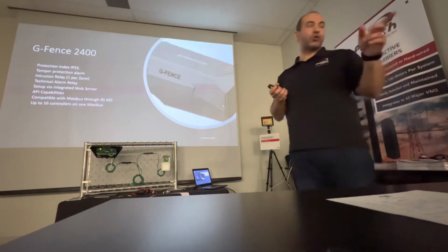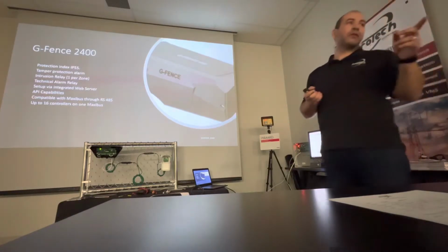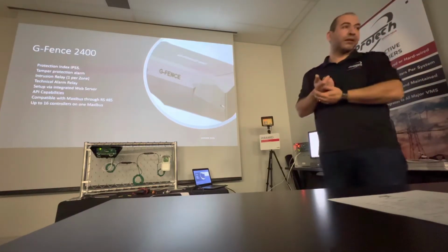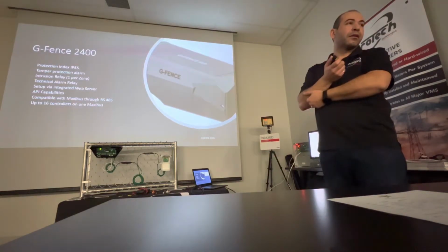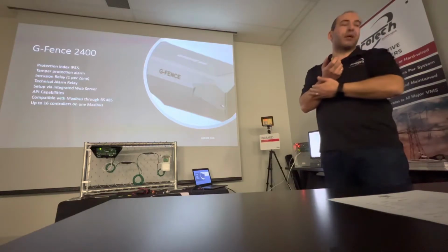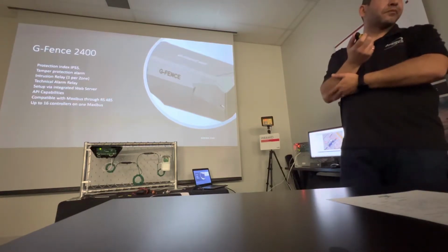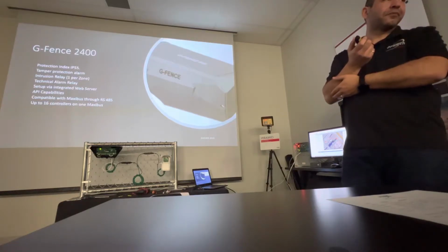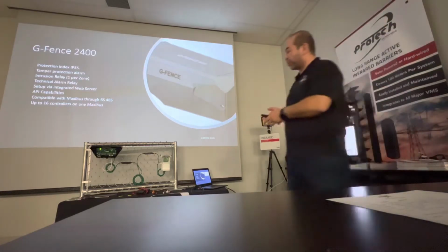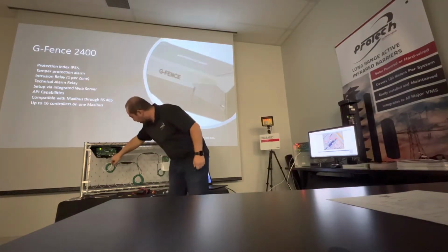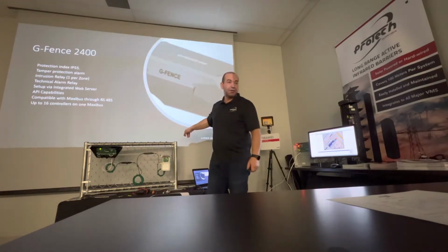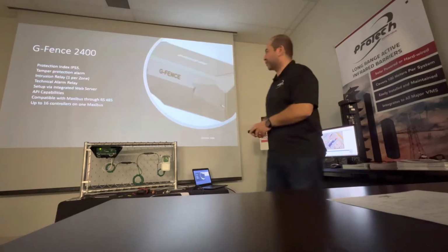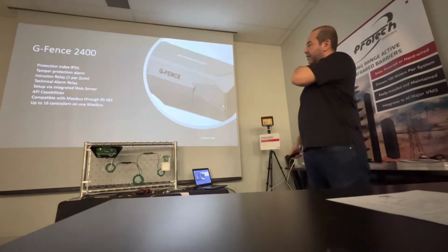Exactly. If you put the control unit inside the building, you ground it, so you can keep going until you reach the end of line. You have to put them on a common ground across, the same common. Because if you do the grounding pin separately, now you have 4 different grounds. You have to keep in mind the data here with the ground. You have to look back on each control unit, so you will have the same ground, one way or the other.